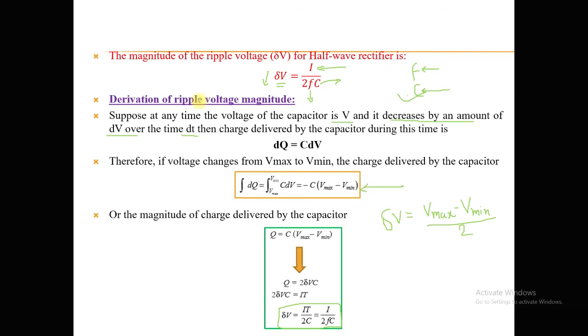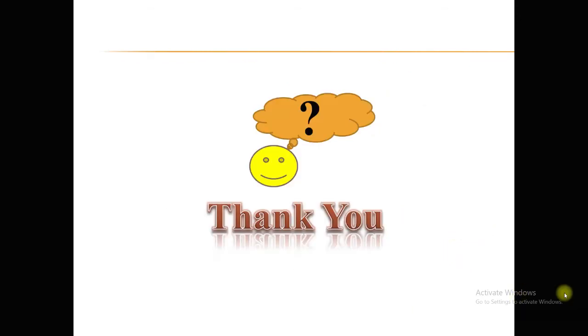Okay, so if suppose I want to test the insulation at 60 kV when the available source voltage is, let us say, 30 kV only, in that case I need to go with the voltage doubler circuits to produce the double voltage. Okay, so in the next lecture we will see the voltage doubler circuit and the voltage multiplier circuits. Thank you.